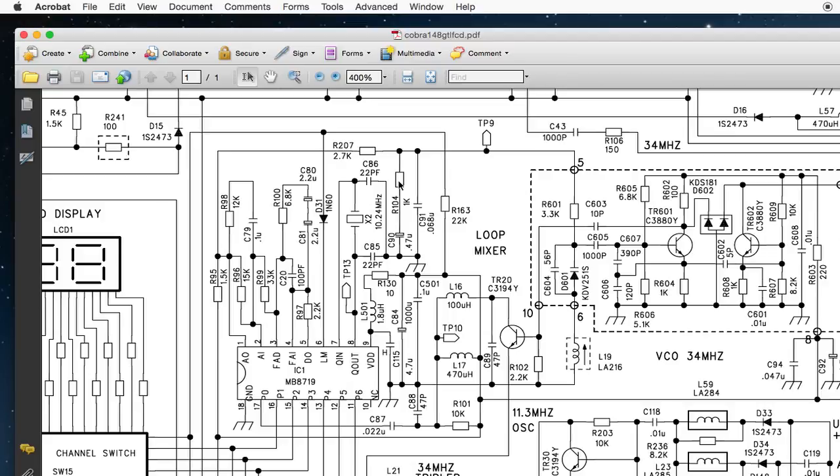If you measure that on an oscilloscope, you can actually see the pulses in some cases. And if you're seeing too much oscillation in the voltage at this point, you might be able to just tweak this and change it a little bit and improve the frequency. Especially if you're doing a PLL replacement or something, you might find the phase detector output from the PLL is slightly different to the original, and it doesn't quite work the same way. You might need a bit of tweaking.